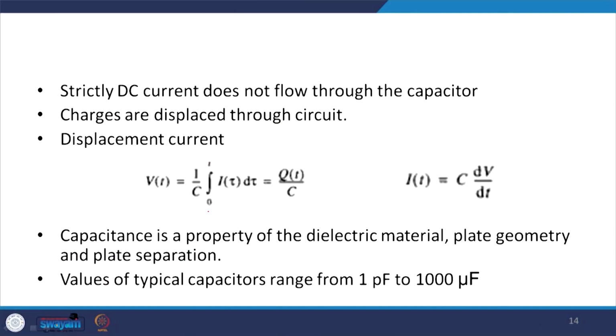And the integration of this current divided by C gives us the voltage, Vc = Q/C, or we can also evaluate I = C dV/dt by differentiating this equation. So, we can see that capacitance is a property of the dielectric material, plate geometry and the plate separation.